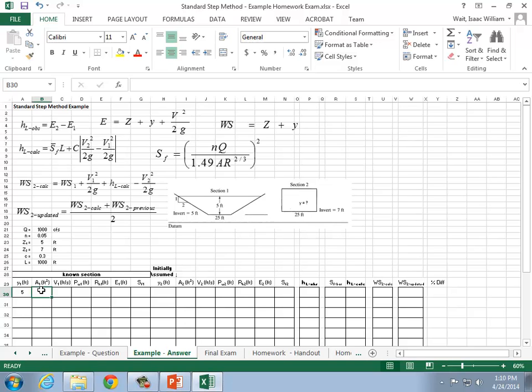We know that the area can be calculated for a trapezoid. That is the depth of 5 times the 25-foot width. Well, instead of keying it in, I'll multiply it by, oh, I must not have it written in there. Okay, 25 plus, then the sides are going to be 5 tall and 10 wide, so plus 5 times 10. So that gives me an area of 175 square feet.